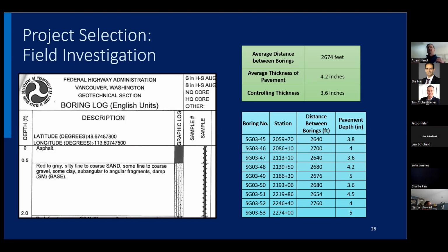And you don't want to go out to do a CIR and not collect enough information to know that you've got locations where you only have 1.5 inches of hot mix, for example, because it's going to change your operations, right? And so part of the point here is collecting enough information. And we heard this repeatedly from each of the agencies that we talked to: if you don't spend enough up front to make sure you know what's out there, it can create hiccups for you as you go to build the job. So again, a good example.